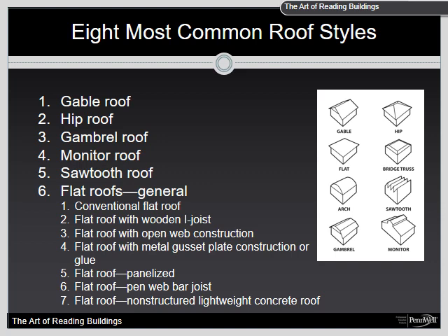Please be aware that trusses may be modified on commercial buildings to look like 2x6-inch rafters on the front side of the building, but in the rear they are normally not modified. Often you can look at the rear of the building, and this will allow you to see the real size of the rafters used in the building.